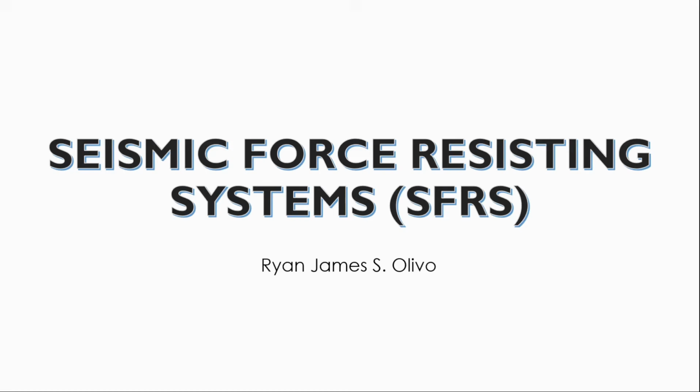Mostly we are in zone 4, so there are some resisting systems that are not permitted. But first, let's understand what this seismic force resisting system is. As you can see, based on the title, it is the systems that resist earthquake or seismic forces. So it's important that in designing structures, they are not only designed to resist gravity loads such as dead loads and live loads, but we should also design our buildings or structures to resist earthquake and seismic force. So now let's continue.